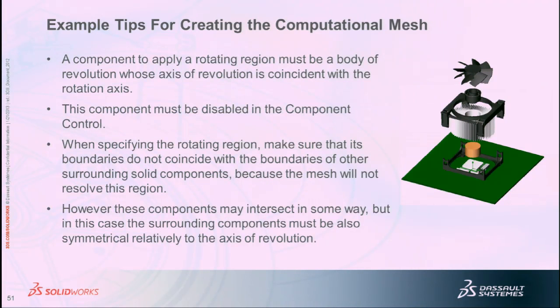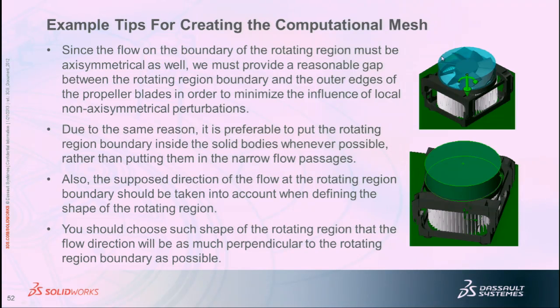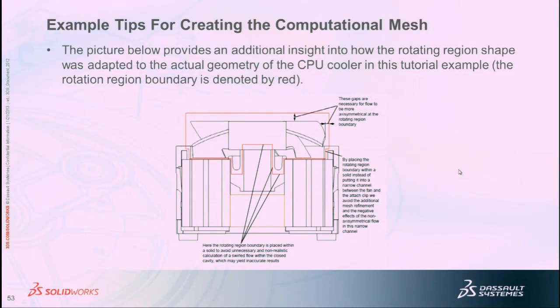Okay? And now here's an example. This is a fan that's actually used in industry. There's a heat sink mounted under the fan, and there's a copper core, that's the orange thing that you see, and then there's a very hot component dissipating a lot of heat right underneath it. So the technique that I've been telling you about for the rotating region was actually used. You can see the solid feature right here. You can see it's slightly bigger than the impellers. This is with a transparency on, this is without it. This is a cross section.